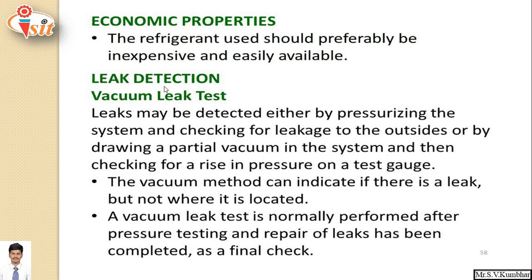Economic properties: the refrigerant which is used should preferably be inexpensive and easily available near to our area. Otherwise, in case of leakage, we have to purchase it from some other countries or some other area, and it may take a long time. That's why it should be easily available and inexpensive in nature.